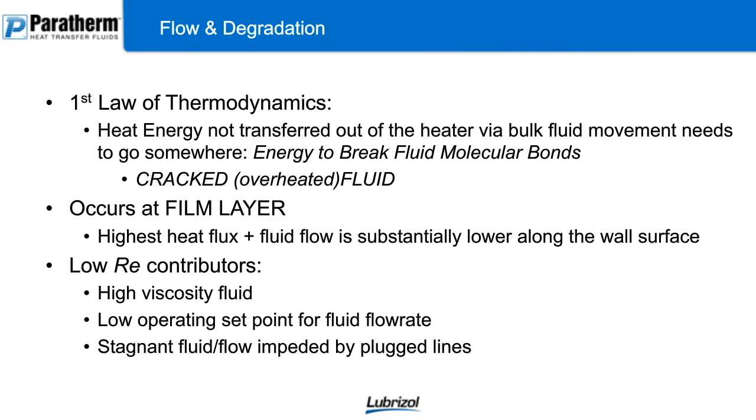Okay, so energy is neither created nor destroyed. That's the first law of thermodynamics. And your heater set point is going to be, if you're operating under normal conditions, a set value. And that heat energy is going to be output by your flame or your heat source. If you don't have proper movement of your fluid to pull that heat away from the heater, the energy is going to go somewhere. And where it's going to go is going to be into breaking your fluid molecular bonds.